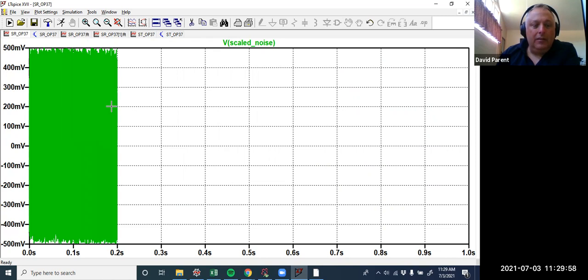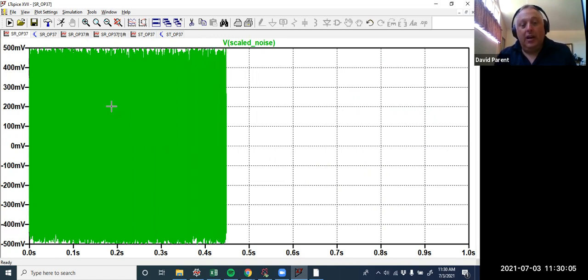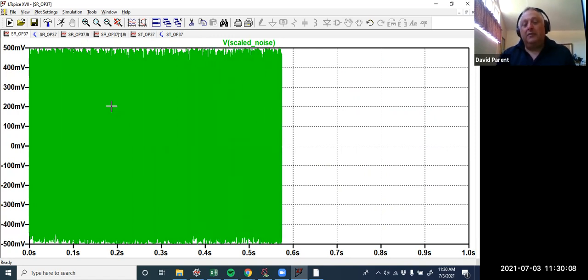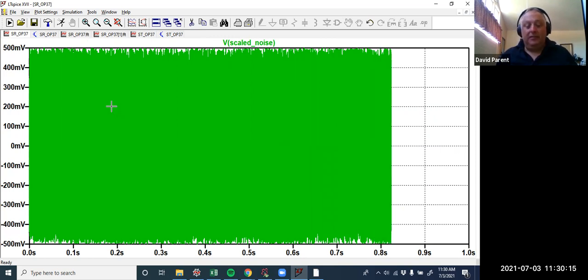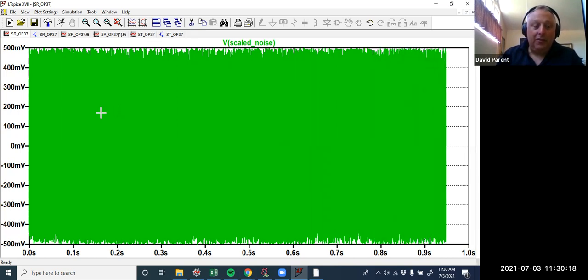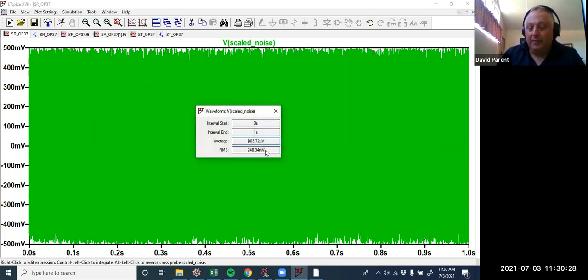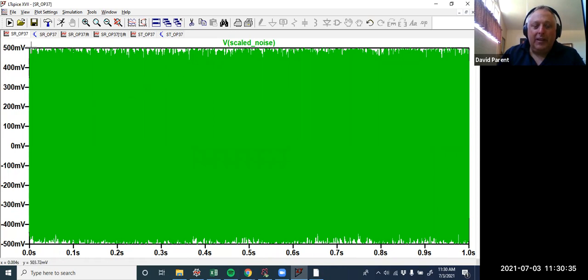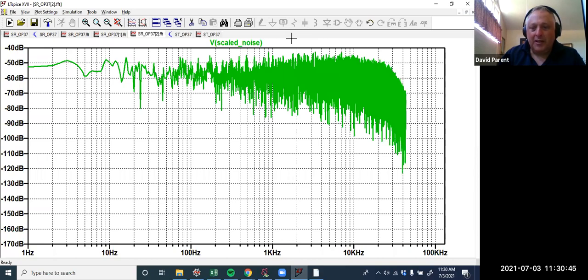So the input noise will be an input, right? And what are we going to change? Noise does have frequency to it, right? And a perfectly uniform noise would contain all the frequencies. There is a way to use a noise source to generate a Bode plot. But the first thing we'll do is just control the RMS. What is the RMS of that noise? So that would be an input. But there's the frequency component of this as well. And that's what I found is a little bit harder to find information on.